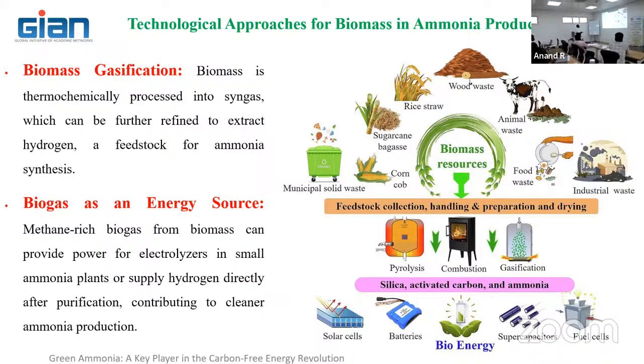So we can produce biogas from anaerobic digestion, which is rich in methane. That methane we can use for the steam methane reforming route or other kinds of routes to produce hydrogen out of it. But when you are using hydrocarbon fuel, the carbon capturing unit is mandatory.